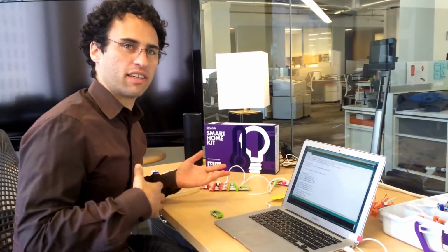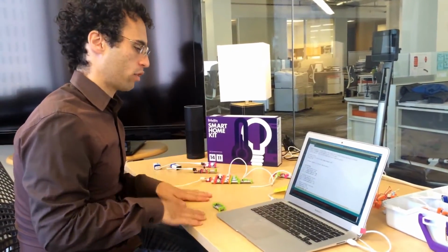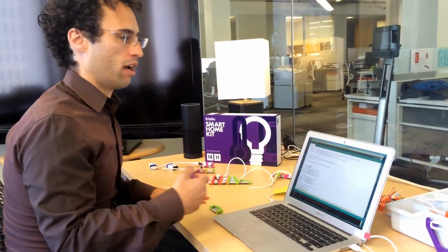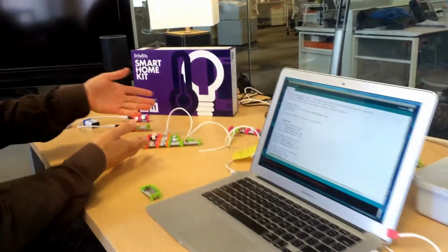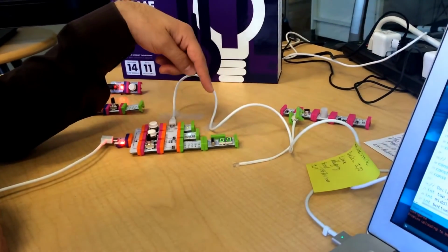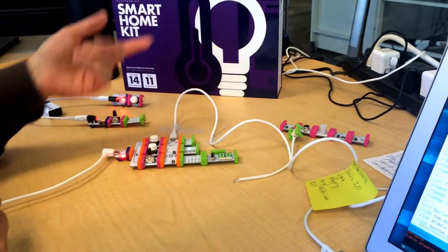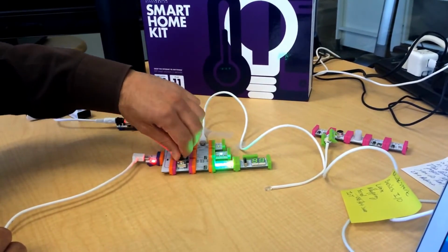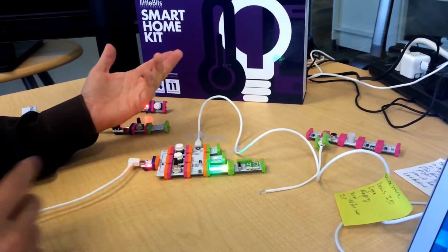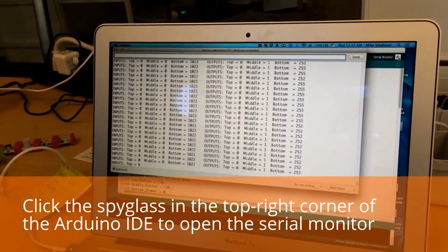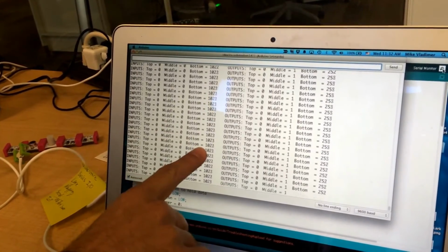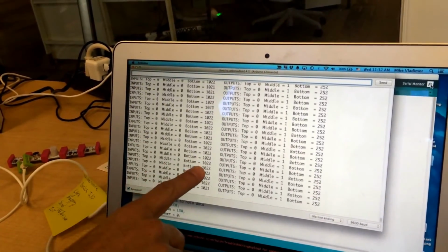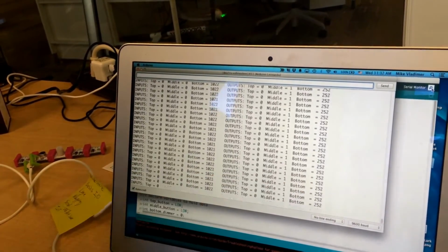Now I'll just show you how you can see that discrepancy between LittleBits values and Arduino values. And that's another fun thing I built into the code. I use the serial monitor to just check those input and output values. So what you'll see is I added just our counter or number thingy from LittleBits so that we can see what this output value is, and it's exactly what we'd expect, right? So when I have the dimmer turned all the way down, it's at 0. When I turn the dimmer all the way up, the bar graph's at the max, it's up to 99. But what does that look like in terms of values for the Arduino? Well, like I said, the Arduino sees that 5 volt signal, that maximum signal, as 1023. On the output, it sees it as 255.